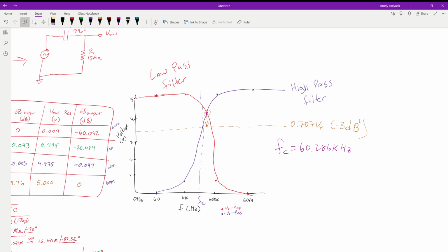One of them is going to be set up for 60 hertz. So when one tool sends in a 60 hertz signal, it's going to see it and go, oh, hey, that's me, blink, and it's going to turn on because it sees that signal. And you're going to filter everything else out. You don't want your circuit that turns on the light to see any of the other signals, because you could have all 4 of them going at the exact same time, but you don't want a 600 or a 60 megahertz signal to trip your 60 hertz signal, because then it would be saying, hey, I've got this tool done, but it's really not. You only want the specific frequency.